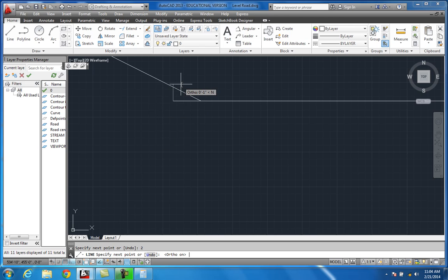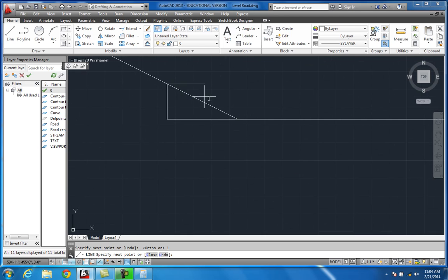It's a little bit opposite if you do architecture quite a bit. It's opposite of a roof pitch. You know, if you had a 5-12 roof pitch, that means 5 up, 12 over, right? This is kind of backwards of that. Angle of repose is always like 2 to 1. You go over 2 in the X direction, and in Y you go up.